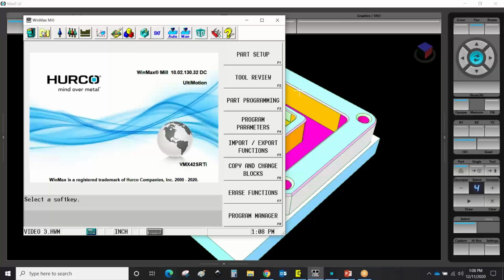Let's say that you started this job on first shift and you ran all day. Second shift comes in, they're running the same program, but one of the drills breaks, and they retouch off that tool, and they go ahead and run the rest of the job out. You come in next morning, you don't know that they did that. You go import from, and they didn't save back to your tool list program. Next morning, you come in, you use the tool list program, and now your drill that was there yesterday is no longer the same. So that's one way we see import from a conversational used a lot.